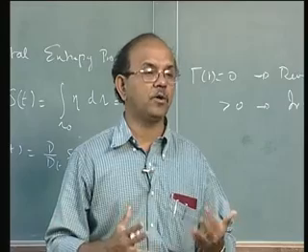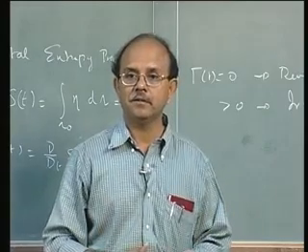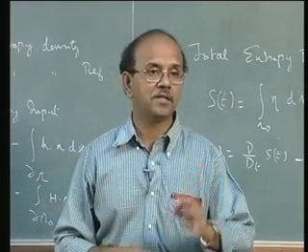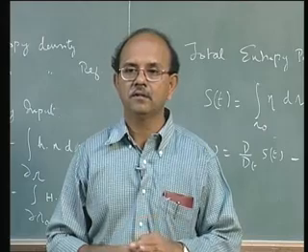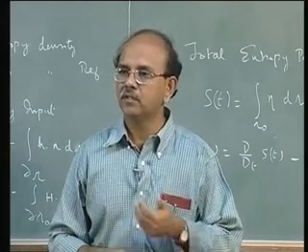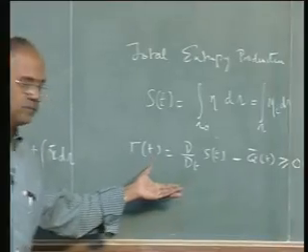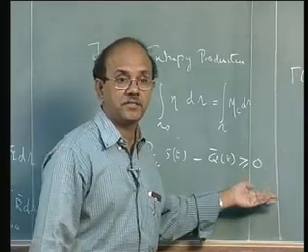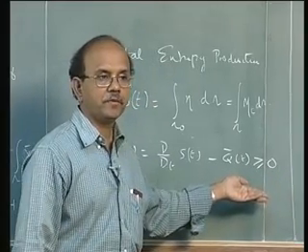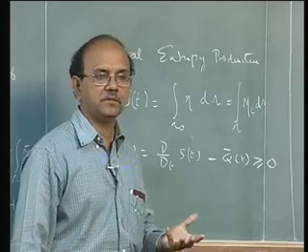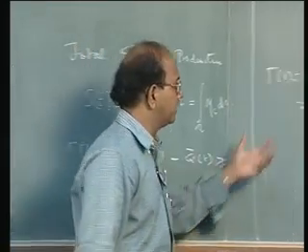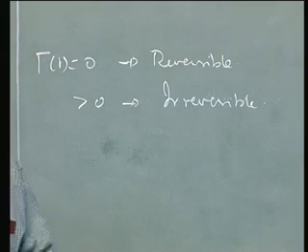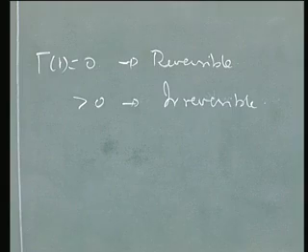This is typically what we are going to later define as the elastic material. In fact, look at the way we are coming to an elastic material. Elastic materials are ones which are basically reversible in nature. Reversible such that the entropy production, here this equation, happens to be 0. So that's the strict elastic material. Inelastic materials, materials which are not elastic, are ones where this entropy inequality holds good, or this is greater than 0. Is that clear?